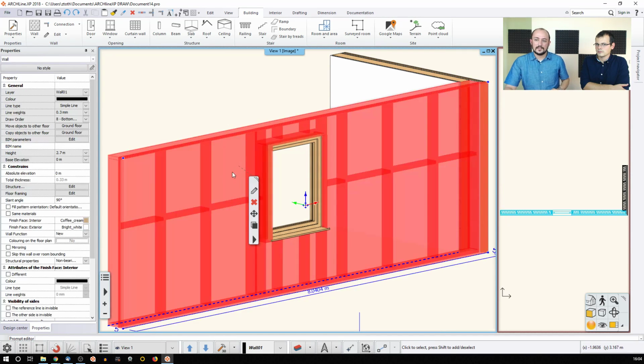The other way to handle specific IDs or any sort of tags for these items is the BIM name. The reason I suggest this is that it survives export. If you export your model into another software to collaborate with other designers, the BIM name is kept. You can also store it into a style.